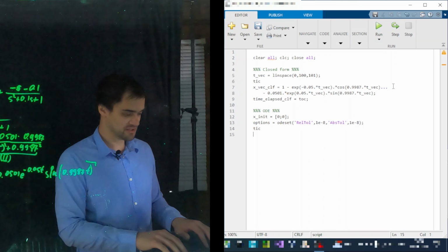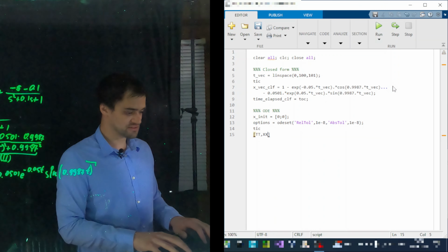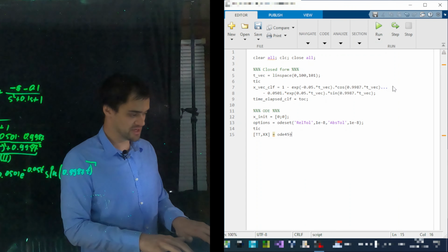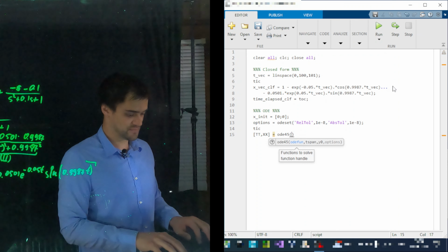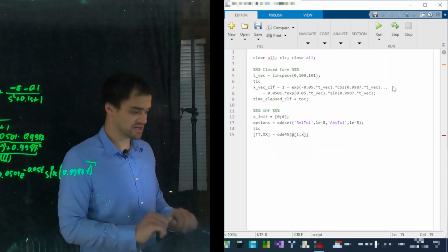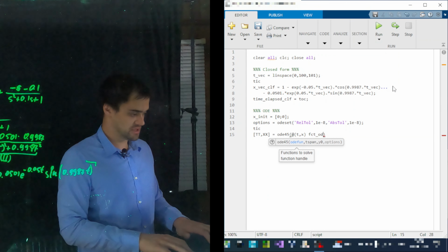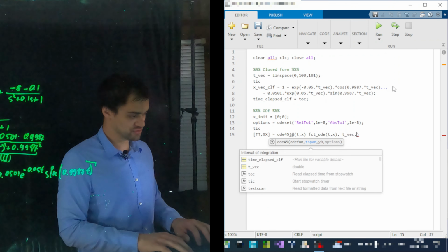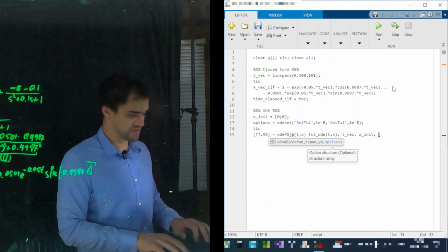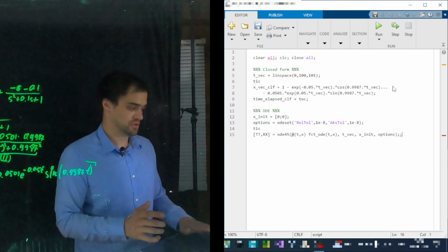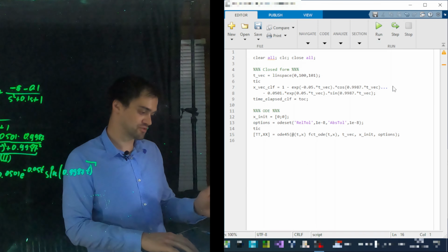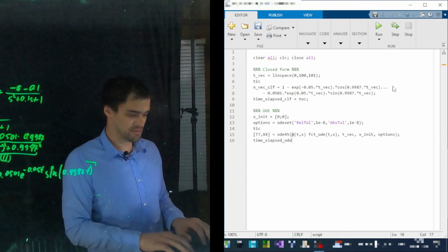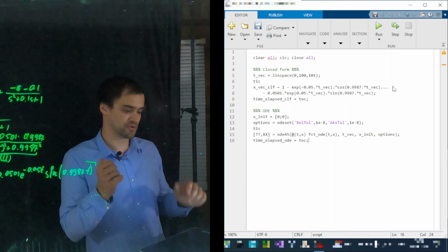So I'm saying tic, and then I'm saying big T and big X are going to be my ode45, which I'm calling now, and I need to be careful. I'm going to pass an argument, which is t and x, and I'm making up a function, fode, which passes only those two. And I want to have my time vector, of course, my initial conditions I need to provide, and my options. So once I have this, I can look, that's going to dive into the function. But afterwards, I have time elapsed, not CLF, I have time elapsed ODE, and this is going to be my toc. So this is my stopwatch again.